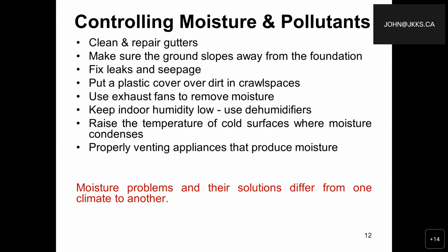And again, as an inspector, often if there were a lot of, we'll call it mildew moisture issues, I would recommend to my clients perhaps the use of a dehumidifier to knock down the relative humidity or humidity buildup in a house. Raise the temperature of the cold surfaces where moisture condenses.